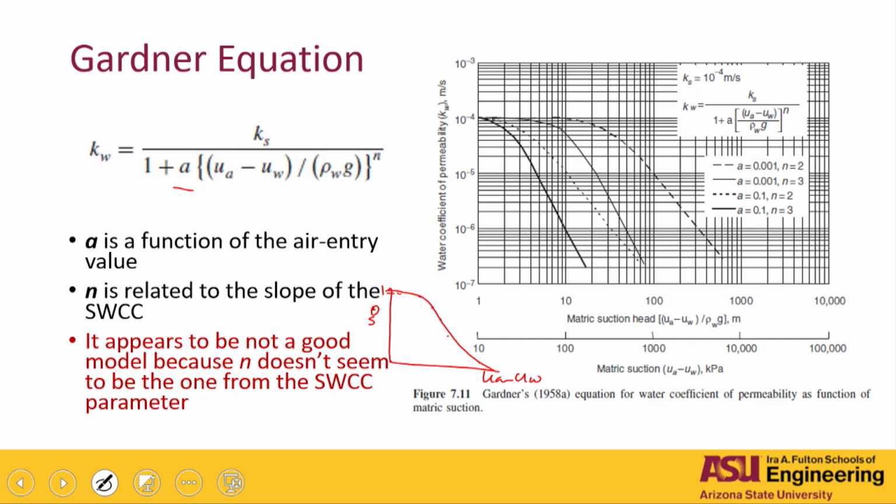For if you get into the Fredlund and Xing equation, you're going to find 4 parameters, a, b, c, and h_r. These are nothing but fitting parameters to the data that you obtain in the field or in the laboratory, right? So this is how you obtain these parameters. You measure the data points.